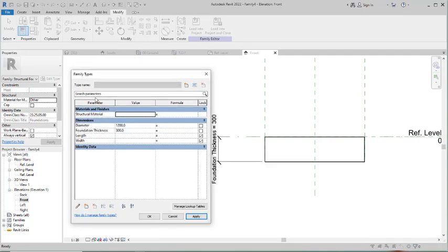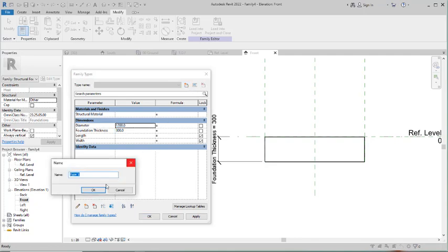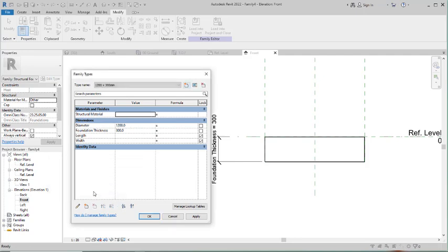What we need to do is create a type name for it. Okay, we will need to create a type name. So we now have this to be 1.2 by 300. Okay, footing size 1.2 by 300 footing size. So we will click in this provisions, this one, New Type, we select that, and then in these provisions we have 1200 by 1200 by, just backspace and use X right there, and then you type the thickness to be 300 as we have in that provisions, just like this. Okay, and then you add mm, which is millimeters. Click on the OK option just right there.